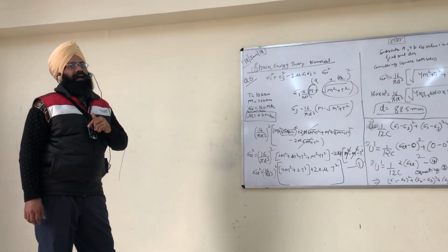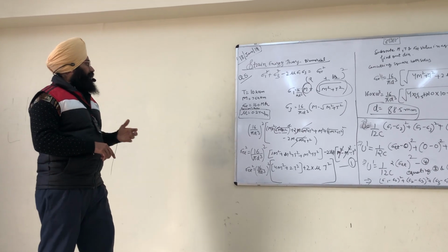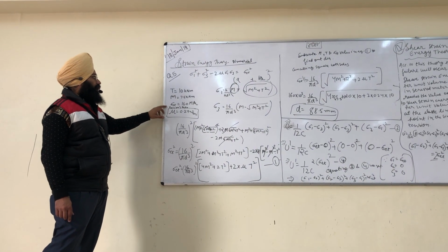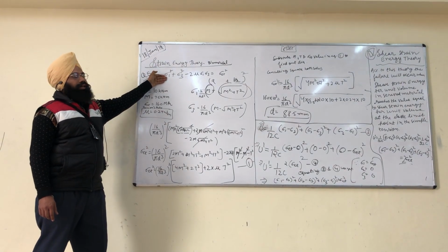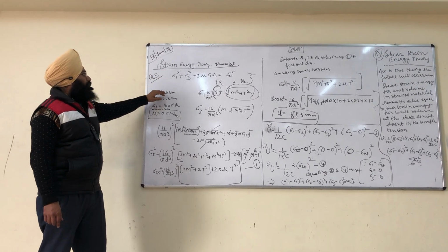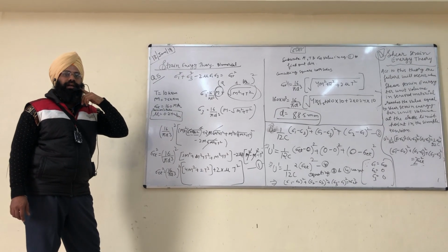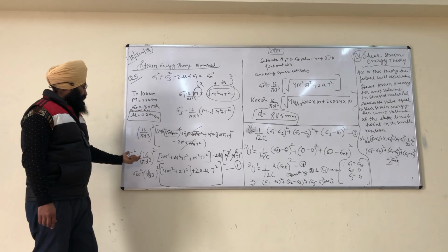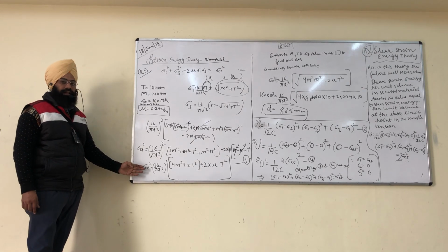For this, the values of the torque and moment are given to us, and the stress at the elastic limit with the Poisson ratio is also given. We insert all these values into the equation of the strain energy theory. When we insert these values, we have to calculate stress 1 and stress 3 in terms of the moment and torque. So we put these values in equation number 1 and finally get this stress ET square equation.